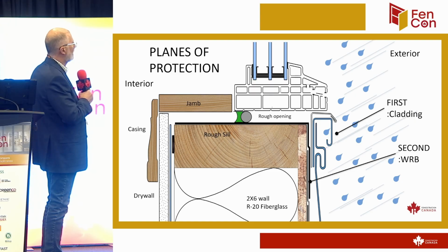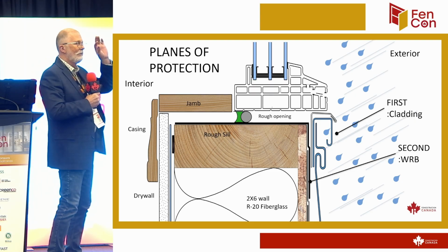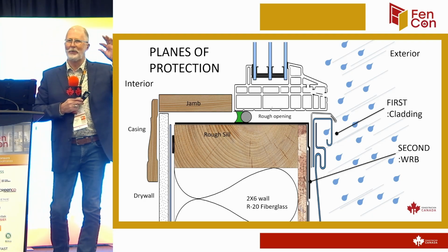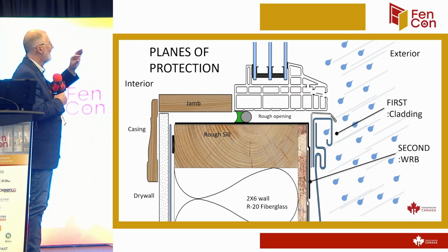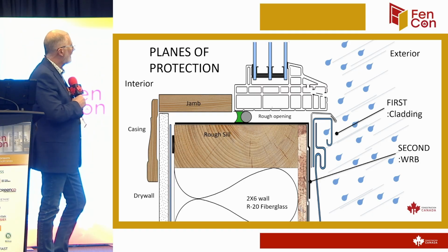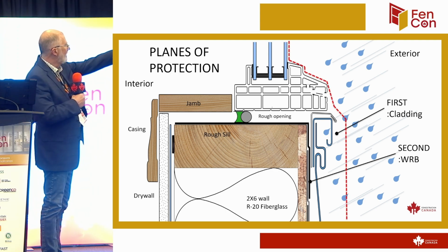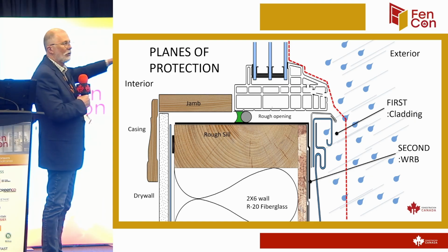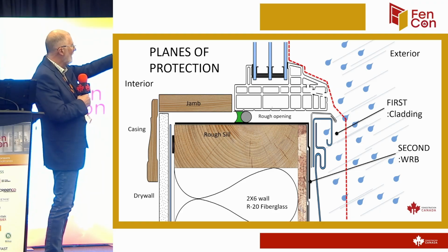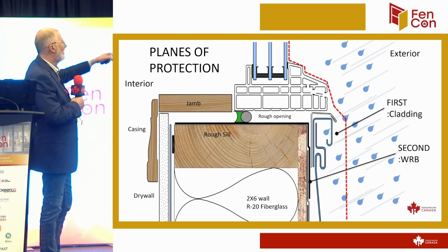Now here's another window. This is a non-flange window, and I'm not showing the shims, but there's shims there supporting the glazing and the glass, but we're not showing that. It just makes it a little bit easier. But you can see the same principle in how this is designed, is that the water on the face is draining away because there's no ability for air to flow through, and if the air can't flow through, it can't carry anything else with it. It can't cool those inside surfaces. It can't bring water in, so that protects that.